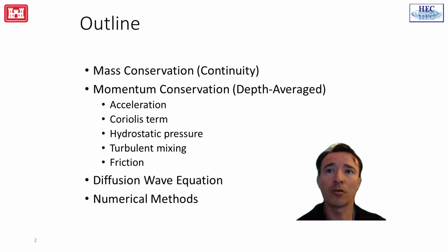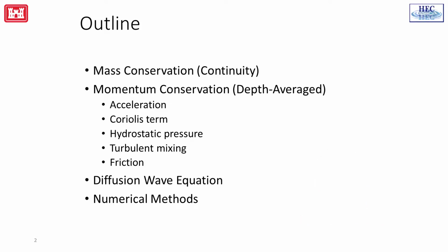I'll start by going over some basic principles such as mass and momentum conservation, which give us the shallow water equations. Then I'll talk about the specific terms in the momentum equation. I'll explain how to derive the diffusion-wave equation, and at the end I'll go over some of the numerical methods used to solve the equations in HEC-RAS.